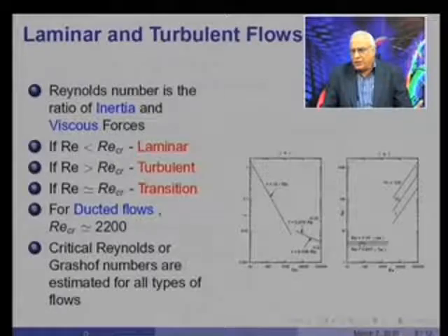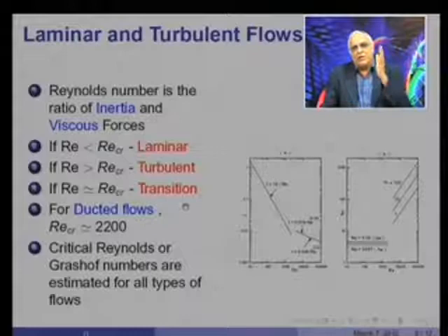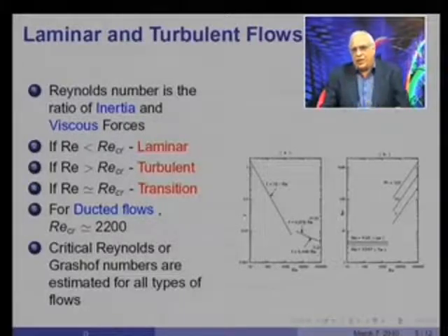All this is known to you in laminar flow. Notice that the Nusselt number is independent of Reynolds and Prandtl number, and it is essentially a constant. But as soon as the Reynolds number exceeds the critical Reynolds number, the Nusselt number becomes a function both of the Reynolds number as well as of the Prandtl number. What about the in-between region? We call it the critical region or the transitional region, in which the laminar flow essentially is converted to a turbulent flow.